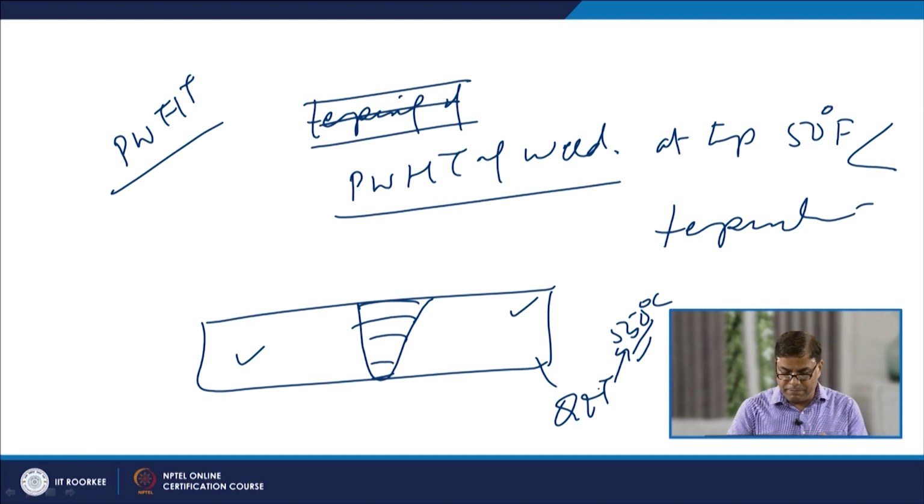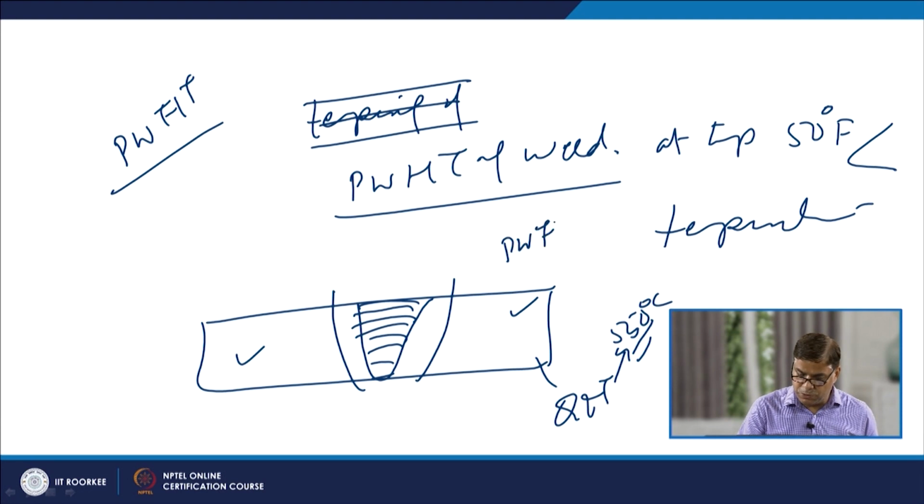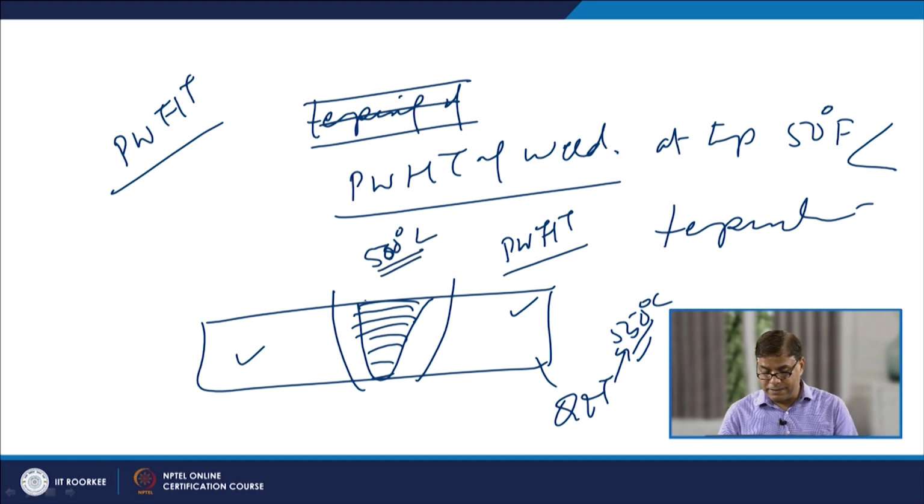If these plates have been subjected to welding, and in order to regain most of the properties lost due to over tempering or unfavorable welding conditions, then the PWHT used for improving the properties of such weld joints, the maximum post weld heat treatment temperature under such conditions should be like 500 degree centigrade, 50 degree centigrade less than the tempering temperature of the base metal.